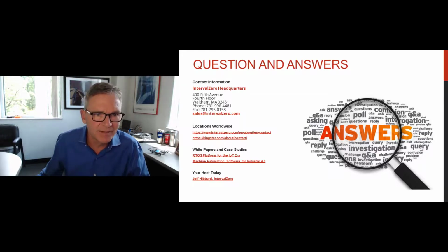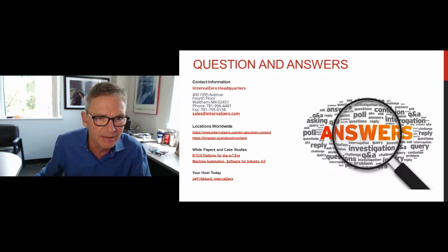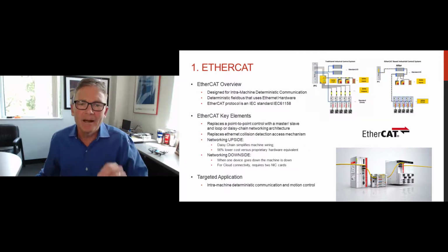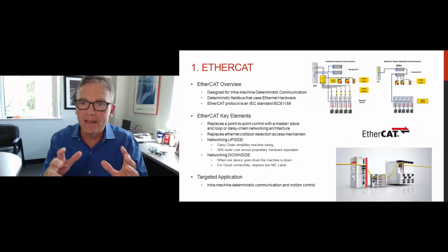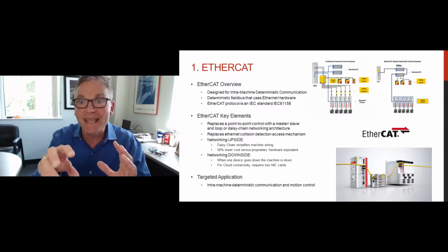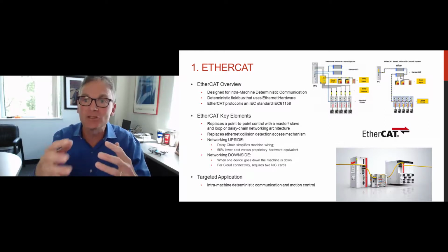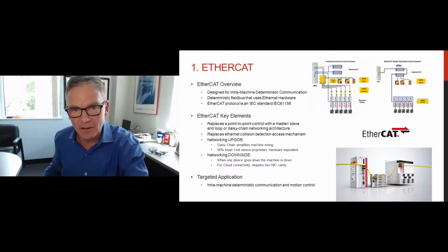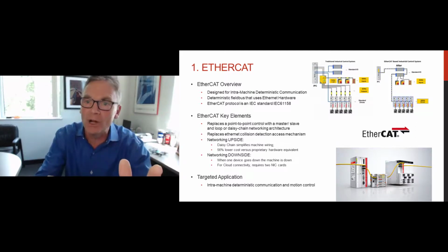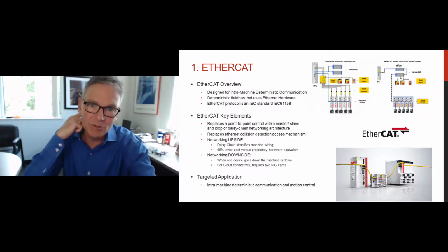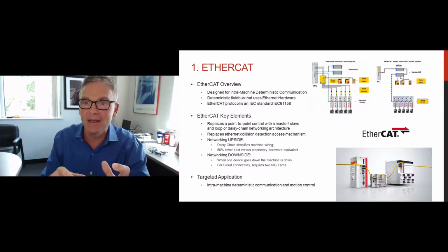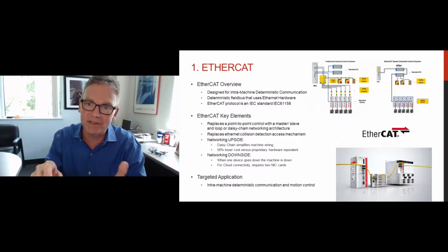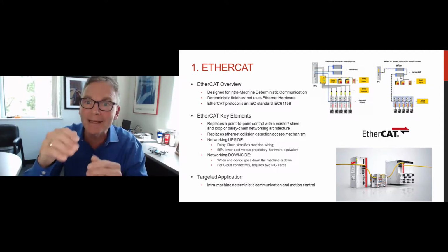All right, so that's an excellent question. I'm going to see if I can go back to my slide for EtherCAT first. Normally, in a safety scenario, you have to have a second network to allow for the safety to occur. In the upper right-hand corner of this picture, you'll see these home run cables. If there's a safety stop, you need a separate network to take care of that. With respect to EtherCAT, the safety protocol, called FSoE, fail-safe over EtherCAT, allows you to plug right onto the same main backbone.